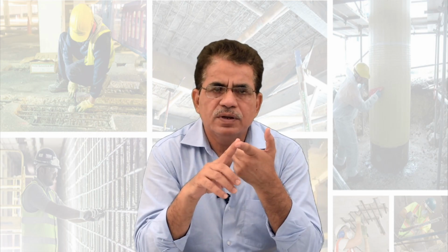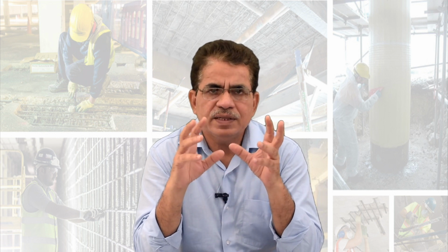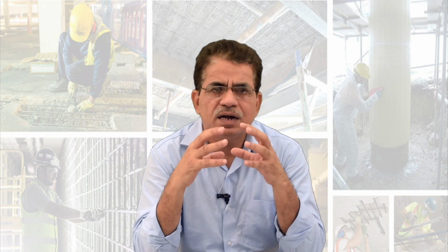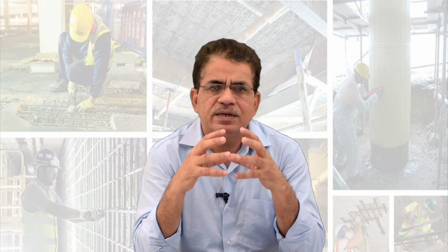First of all, we should be well aware of the properties of the materials, and when you are using different materials in combination, then it becomes very important, because if there is a large change in the characteristics or the properties of the two materials that are being used together, then there will be a problem, because due to temperature changes there will be a different behavior of the material due to different thermal coefficient of expansion or contraction.